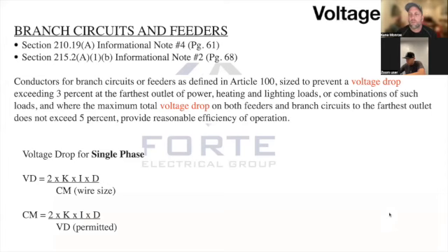So voltage drop is not a code requirement. In two parts of the code, it shows up in an informational note, but you've got to remember informational notes are not enforceable. They're just kind of like suggestions. So it only shows up twice and it's a suggestion.